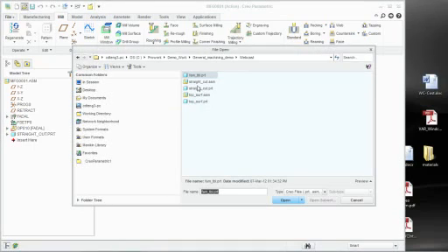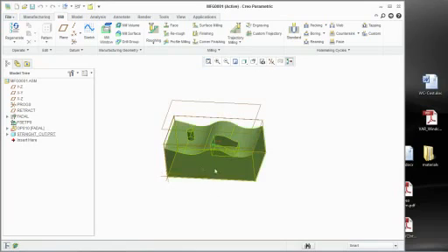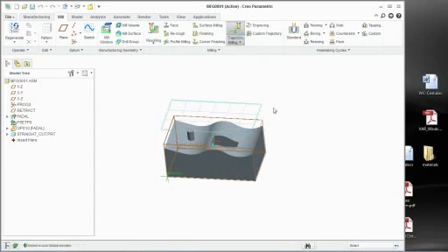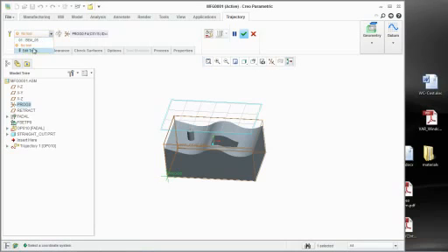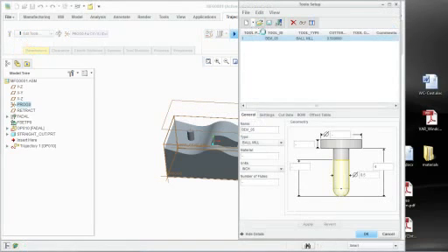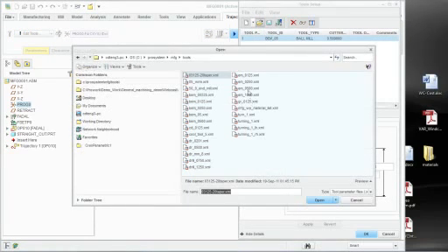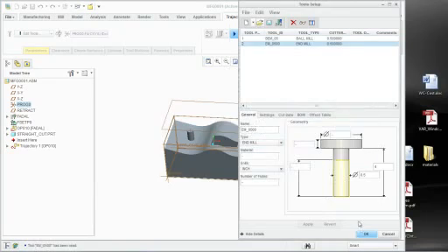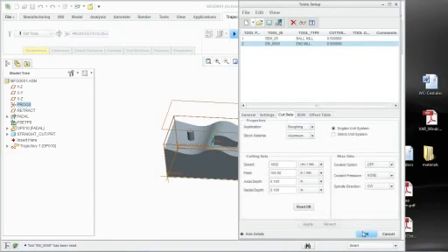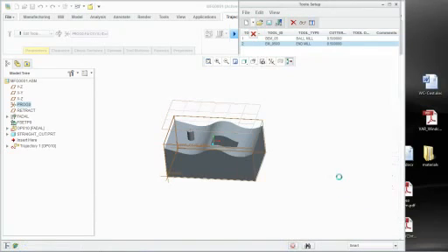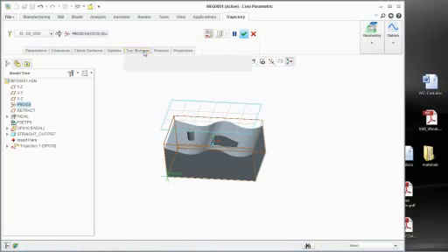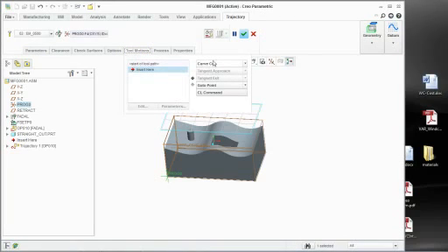One thing, let's do this here real quick on this. Let's do it right here. I'm going to create a quick trajectory mill, or trajectory milling toolpath. I'm going to go ahead and use, there we are. Cut data is already filled out, even though it might not necessarily be right. We'll say tool motions, and I'm going to go ahead and pick the edges of this part.